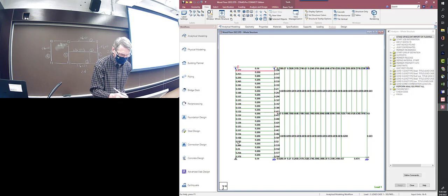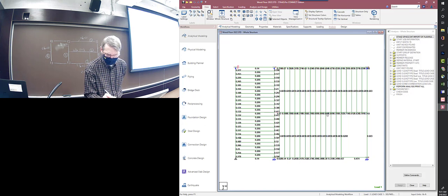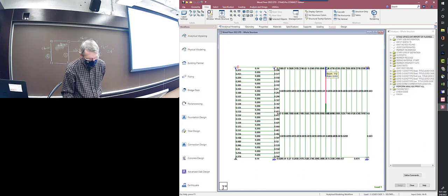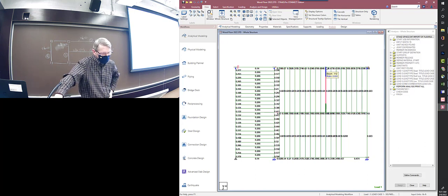The shear again is the higher value. That's strange. I'm a little bit surprised that the bending moment doesn't control in this. You would think it would, right? Why is the bending moment showing so low? And here, okay, here it's a little higher. Here it's 0.8. Okay, that makes sense. This is only 0.4. Here it's 0.75. For the shear, it looks like the shear controls in these. So I don't know. Maybe we're not reading the bending correctly somehow.